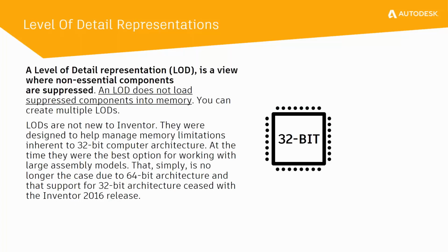Now the other representation we want to talk about is level of detail, or LODs. These are in some ways similar to design views, but in other ways different. It's a view where, again, non-essential components are suppressed, and an LOD does not load suppressed components into memory. The reality is that level of detail came about with Inventor due to the limitations associated with 32-bit computer architecture.